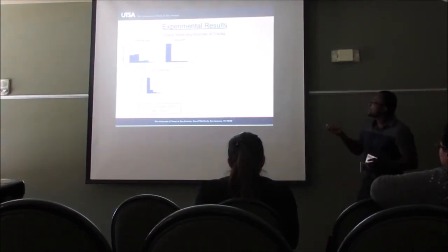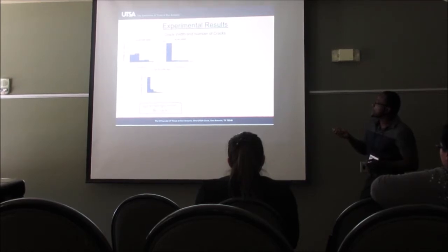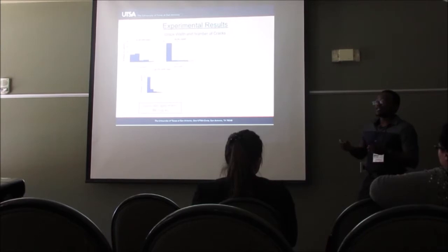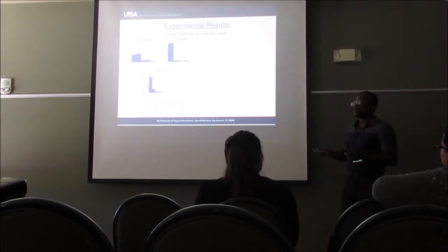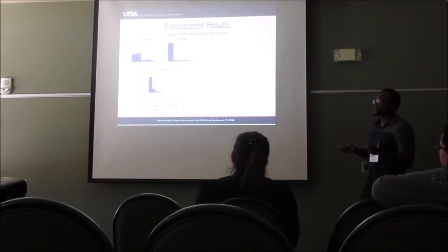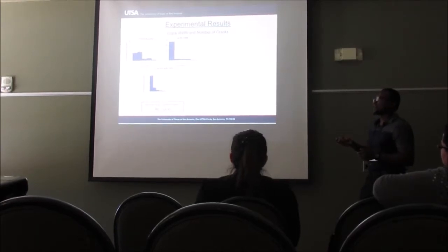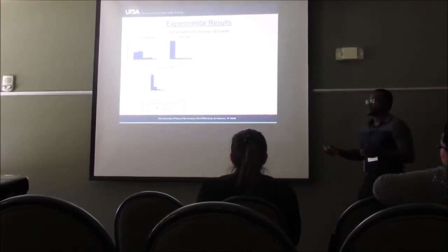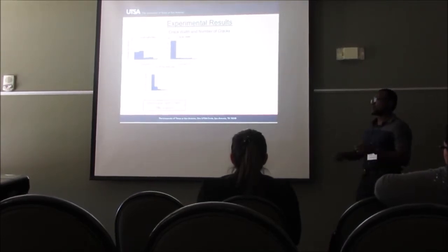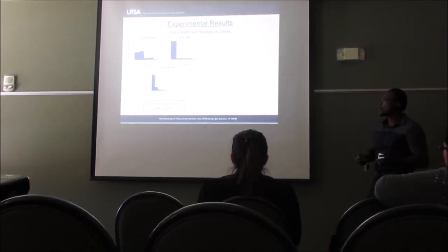And looking at these cracks, the problem that we observed for the spiral bars is that we did not meet the maximum allowable crack width. So if you see, the maximum allowable crack widths were 0.016 and 0.013, and almost at half yield point with the spiral bar, we're already exceeding the maximum allowable crack width. So that was a big problem in concrete design that we needed to take a next step and see how we can fix that problem.